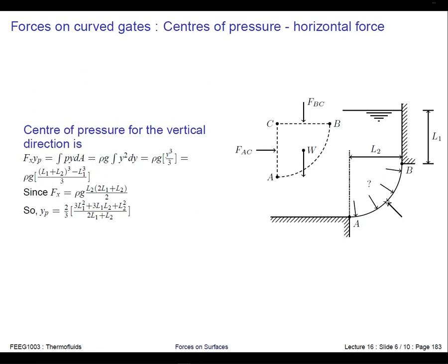So we do this by doing the same thing again and working out the centres of pressure in the horizontal and the vertical directions. So we need to work out where the x force is acting. What we're trying to do is work out where, if this force is acting in all of these directions and it can be taken to be this particular force, where does this particular force originate in here?